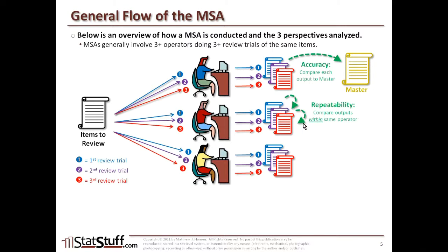That's testing for repeatability. Again, comparing the output within the same operator. Reproducibility is looking at when you're comparing that output data across the other operators and the outputs that they had. That's doing the comparison between operators. So here's where we account for the accuracy, repeatability, and reproducibility.